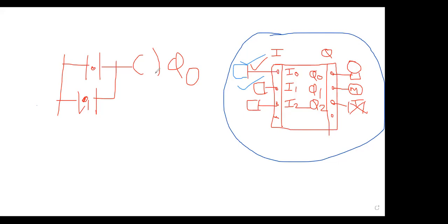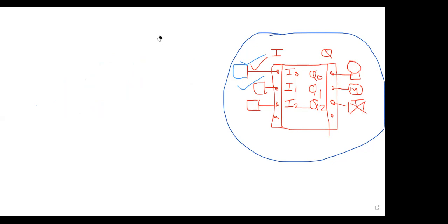It will be on, correct, very good. So it is getting on. It means, according to the client, as per interlock, this program is wrong, isn't it? This program is wrong because the client told you, press a single switch, motor should be on. Here you press both switches, motor is still on. Your program should run for the given conditions only, not for any other combination. So there is one gate, that is XOR, which is for interlock.